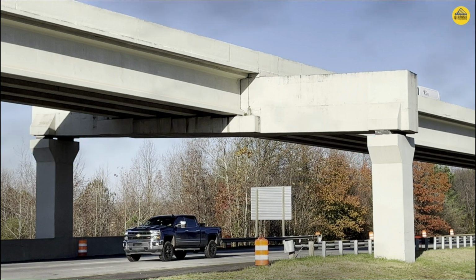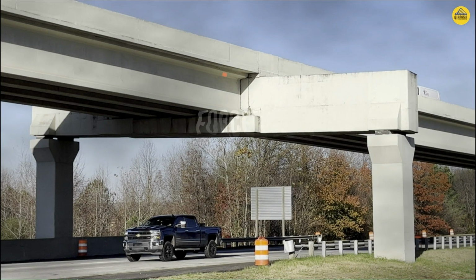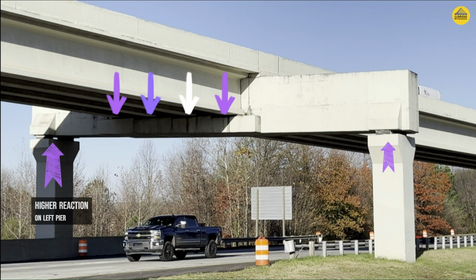Let us now discuss the force flow associated with this structure. All the vertical reaction from the superstructure is transferred to this corbel that is attached at the bottom of the portal cap, and via corbel action, all these vertical and horizontal forces are transferred at the ends of the portal cap onto the elastomeric bearings and finally to the pier. Also note that reaction on left pier is higher than reaction on the right pier, simply because left pier is more close to all these superstructure girders than the right pier.